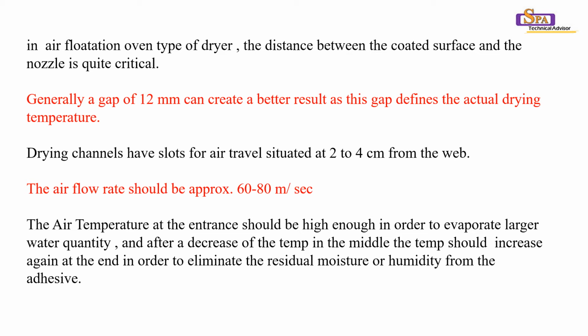The air temperature at the entrance should be high enough in order to evaporate a larger water quantity, and after a decrease of the temperature in the middle, the temperature should increase again at the end in order to eliminate the residual moisture or humidity from the adhesive.